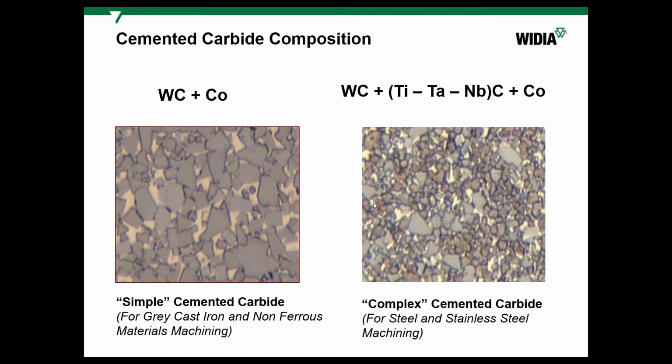chemical and thermal resistance to steel when we machine steel, especially in turning, because with the bigger heat, steel, which is a combination of iron and also carbon, is reacting with tungsten carbide. So in order to resist that, we add additions like tantalum or tantalum niobium carbides and also titanium carbides. And basically the substrate or the tool material at that time, because coating was not invented then, increased chemical and thermal resistance to steel, and made it possible to achieve higher cutting speed, higher productivity.